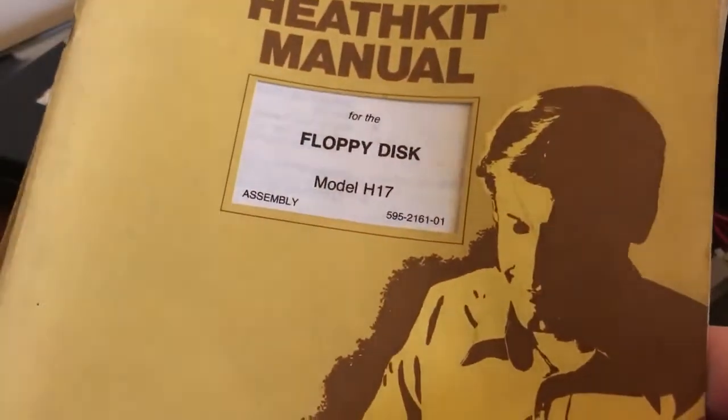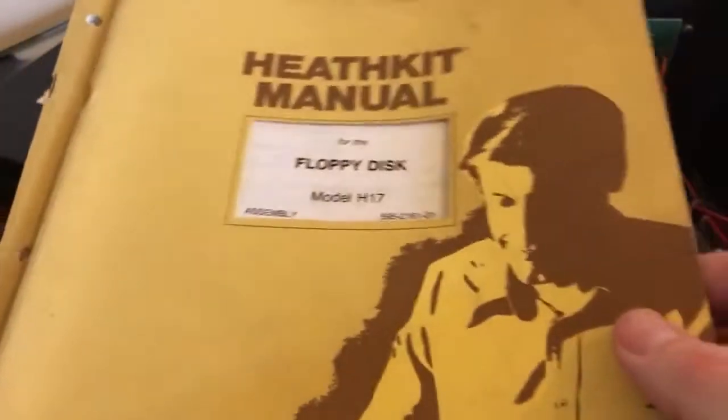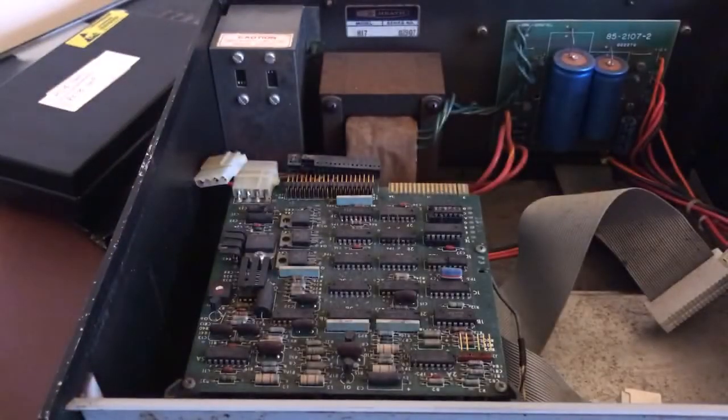I didn't find those online actually, so we need to maybe scan those in and provide them to the community, but I should be able to run some of the diagnostics to check on the state of what's happening. We should be able to see at least the sector pulses coming out on the scope and things like that, just to check the drive's basic functionality before we try and put a disc in there. I'm even tempted, now I've got the serial port working with that faulty USART replaced, to try and get hold of a copy of the short loader that allows you to load software, so I can create a new disc and maybe try and hand punch an old floppy into some of the 11 hard sector holes, might be possible.